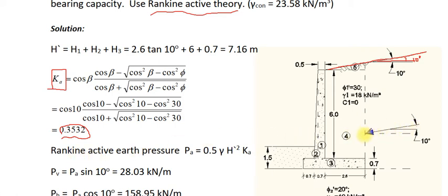Then we have to compute the force. The force here is computed as a resultant of a distributed horizontal load. The H that is included in the resultant is computed from here at the edge of the retaining wall, extending the vertical line to this point on the tilted surface of the soil.